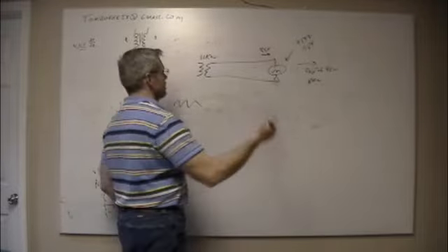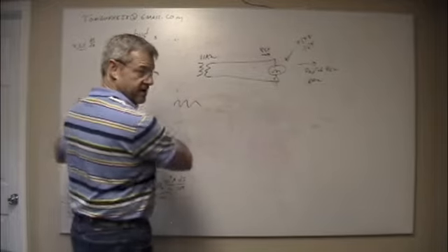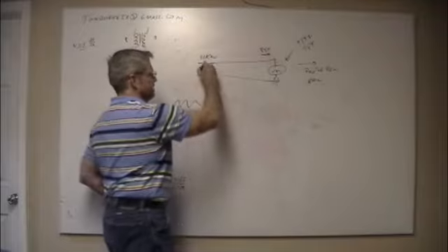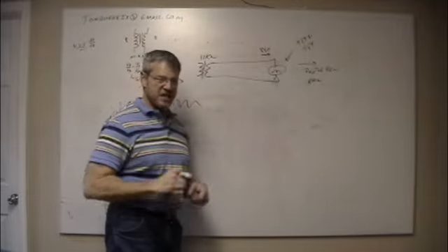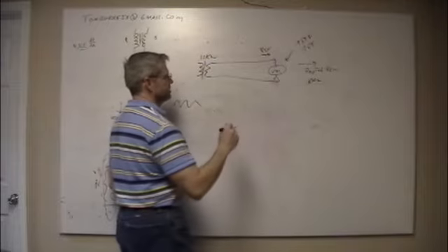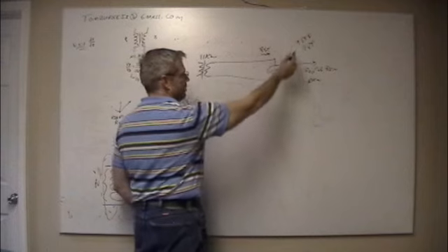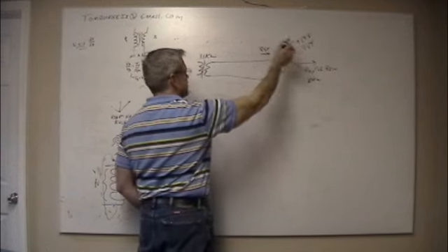Okay. But it's not a purely resistive load for all the reasons we talked about here. And what's going to happen here is you've got this inductive core that we talked about, and it's going to get hot. It's going to heat up. It's going to do all sorts of crazy things because of magnetic hysteresis. And so now I need to divide that by 0.7.